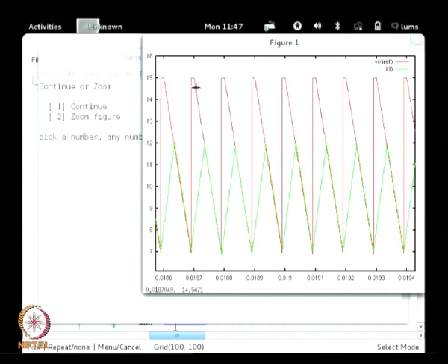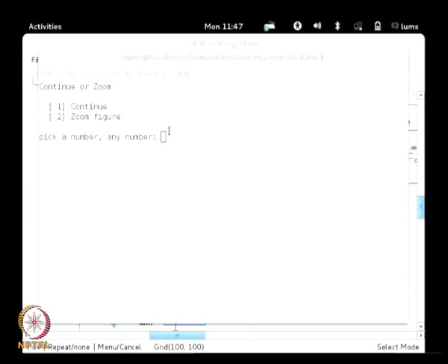For the duration of the pulse width of the clock, the capacitor is discharged and you see the falling ramp. And when the inductor current rises and meets with the falling ramp, the SR flip flop is switched off and the inductor current starts falling down like that.